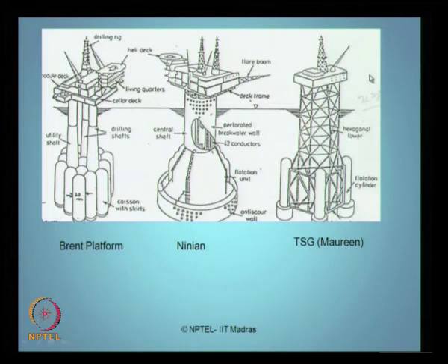You can also see these structures are very massive in size, and because of their weight, which we call the colossal weight of this platform, they are installed in the sea without any pile supports. They rest on the sea bed by their own self weight.